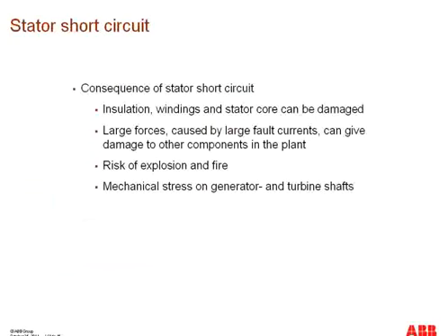Short circuits in the generator will also cause large fault currents, and these fault currents will result in large forces that will give mechanical stress to other components in the power system. There are definitely risks of explosion as well as fire, because there are lots of inflammable materials in and around the generator, which can catch fire and damage property as well as human life.